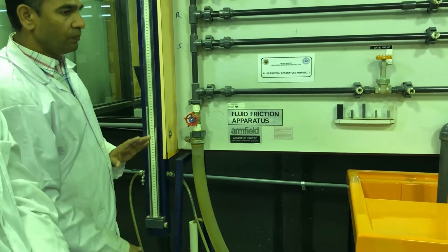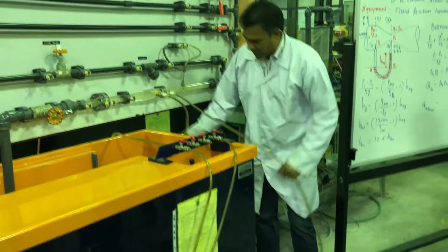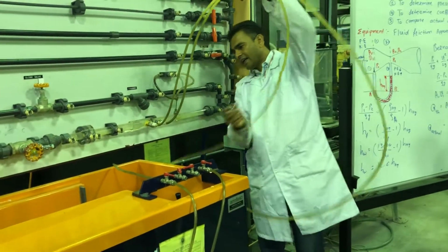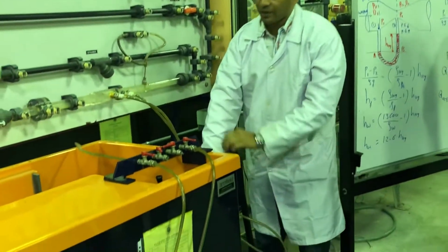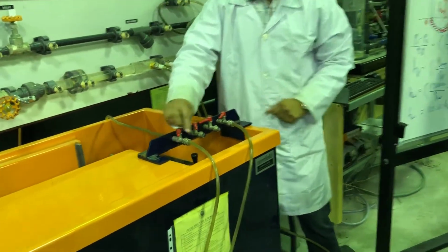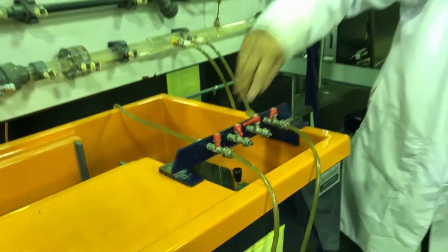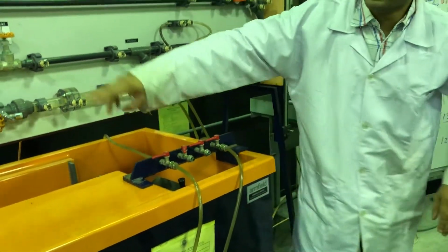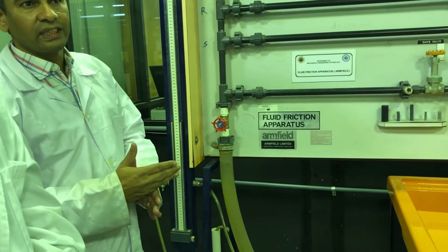Now we need to check for air. Is there any air inside? So check these pipes and check for air like this. If there is air, it will come up. So keep this open. I found air here. Okay. If I close it, the level is the same. You can see the mercury level is the same. In the exam I found this.